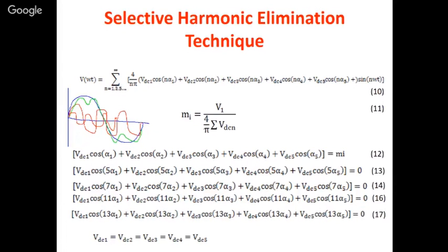So we are not worried about higher order harmonics. They will not change our voltage much. The lower order harmonics are dangerous. For a single phase system, the third harmonic is the deadliest. For a three phase system, the fifth harmonic is the deadliest. So here we are considering a three phase system.